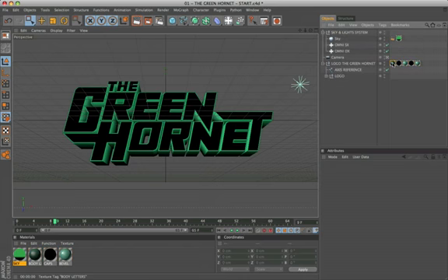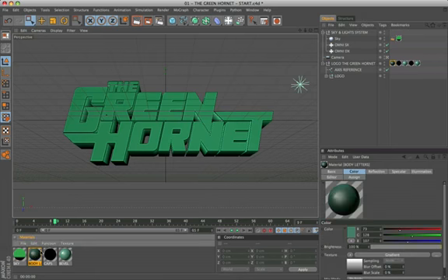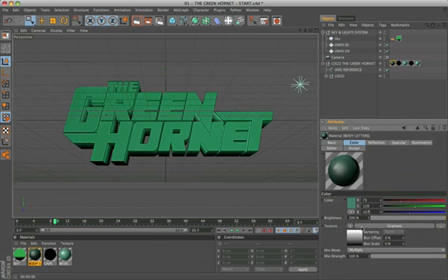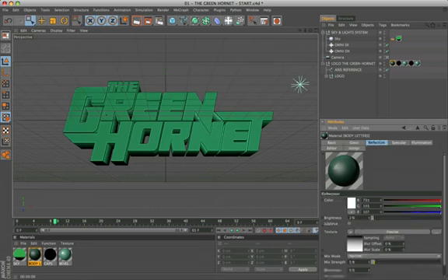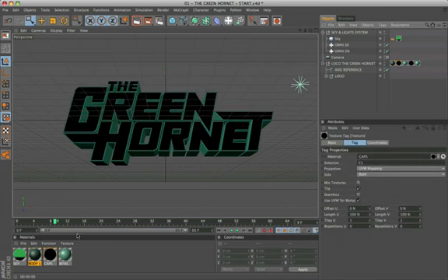The first material gives the basic colors of our logo. The values of the green color are 73, 128, and 107. The gradient was added, in multiply mode, to obtain this position on the logo. We also add a reflection with value 3. Apply a Fresnel texture. The specular channel has the default values. On cap start and end, we applied a simple black material.